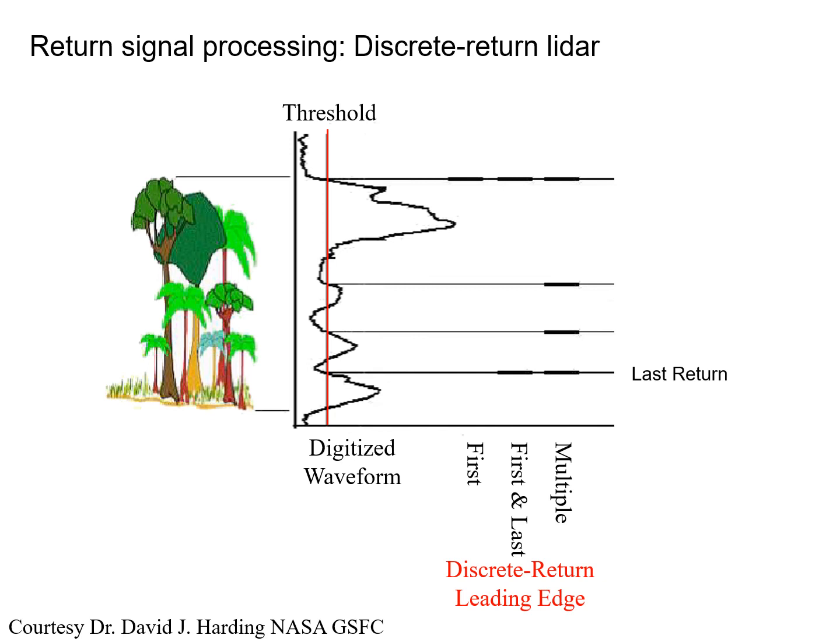Later, first and last return sensors were developed. So you get that first return, and then the forward edge of the last return, when you increase past that threshold, that is also recorded. Why the first and the last? Well, because if you're looking at things like vegetation, what you want is the height or elevation of the top of the canopy and the height or elevation of the ground surface, and that's how you get them.